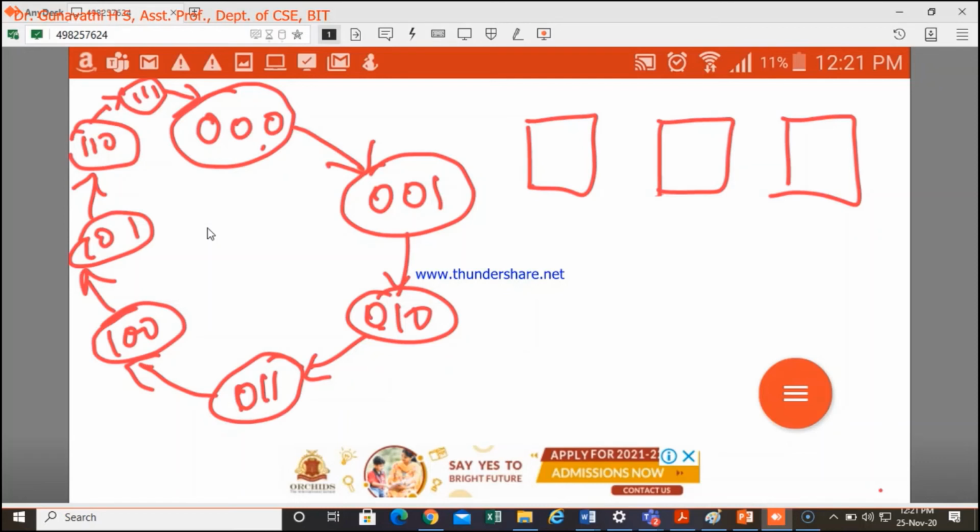This is the most significant bit. If I'm naming this as A, your truth table will be ABC. Then the flip-flops, you can write in any way. The inputs may vary. Or else I can write this as CBA, where I make A the least significant bit. So your implementation will be like this.